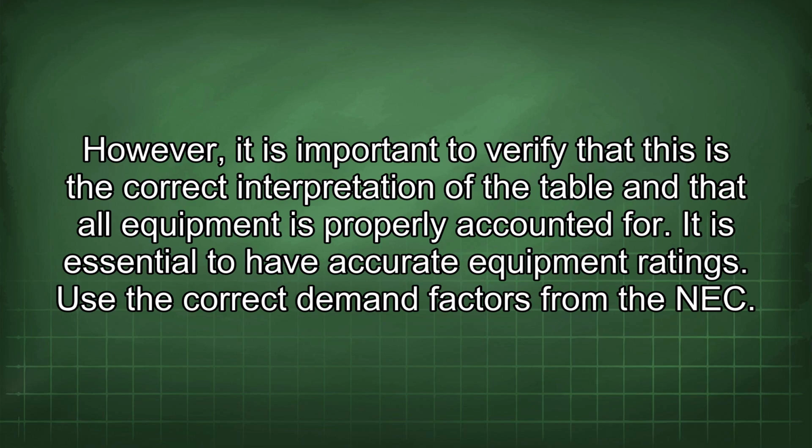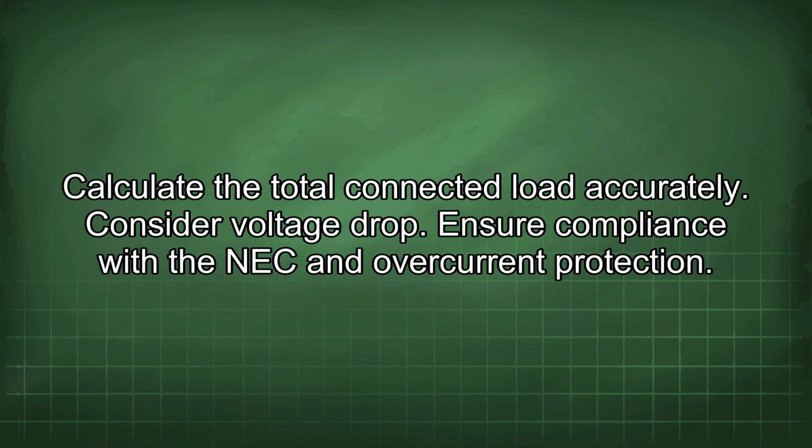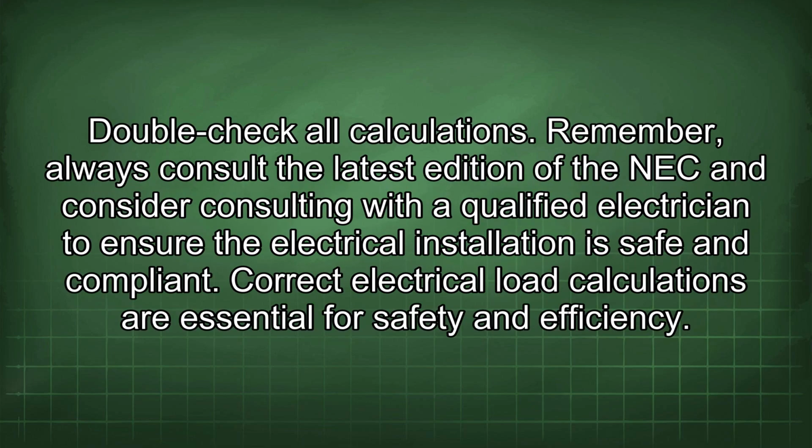Use the correct demand factors from the NEC. Calculate the total connected load accurately. Consider voltage drop. Ensure compliance with the NEC and overcurrent protection. Double-check all calculations. Remember, always consult the latest edition of the NEC and consider consulting with a qualified electrician to ensure the electrical installation is safe and compliant.